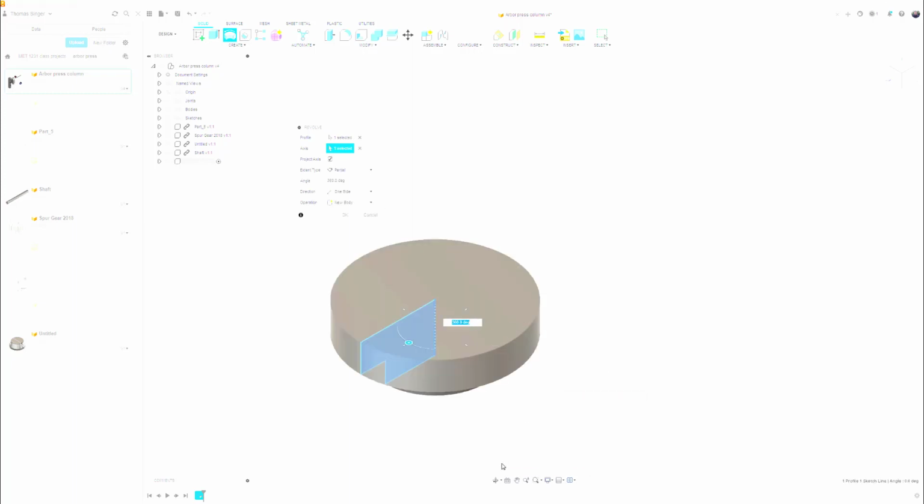And so that's our ultimate shape of our object. We'll then finish our sketch and revolve this particular object. Now, a lot of times what will happen is that it's going to ask you to select the shape, and slide this over. And it also wants to know where the axis is. So I'll pick that center line as the axis point. And there you can see how it's going to revolve at 360 degrees. And it's a new object called a new body.